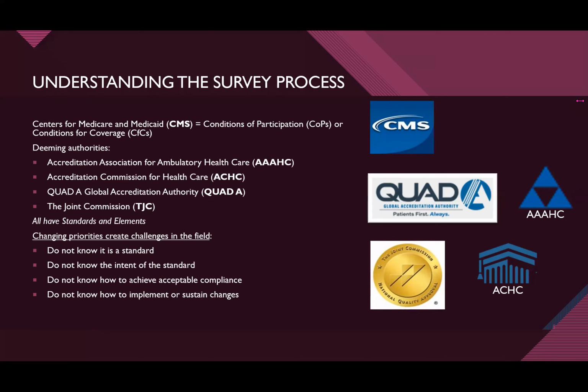The example is that fire doors are required to be checked annually. You need someone, it could be in-house, who's knowledgeable, to inspect the 90-minute doors and the 45-minute doors that you have in your facility; that's required annually. And I've seen some of these reports and there are deficiencies. There are things missing. They don't latch, or the labels are painted, or the rating isn't clear, or it's not the right rating. So there are deficiencies on that report. And the standard says that you will have those addressed, that you need a plan of correction, even on these annual inspections, and you need to get that fixed.